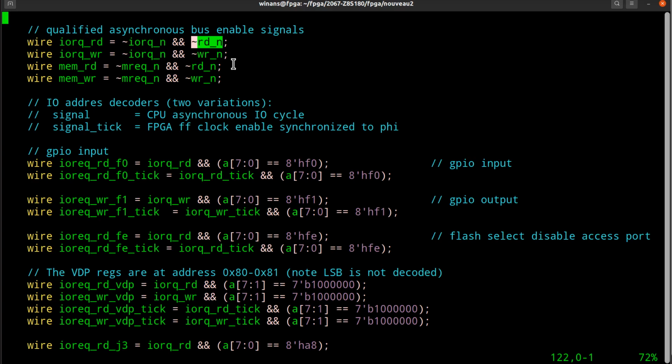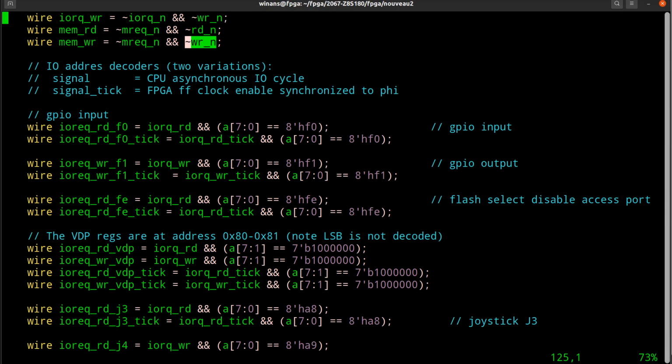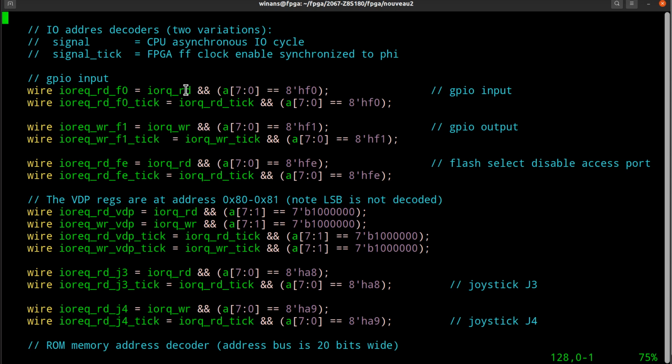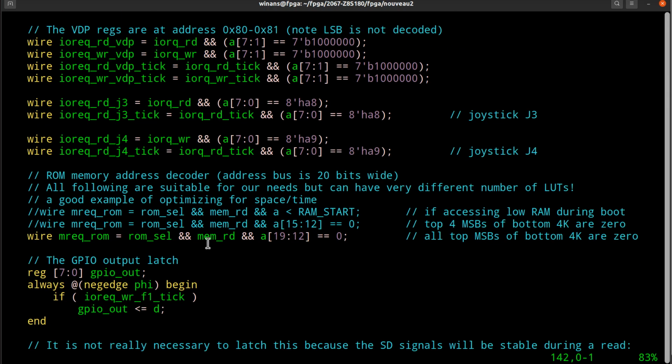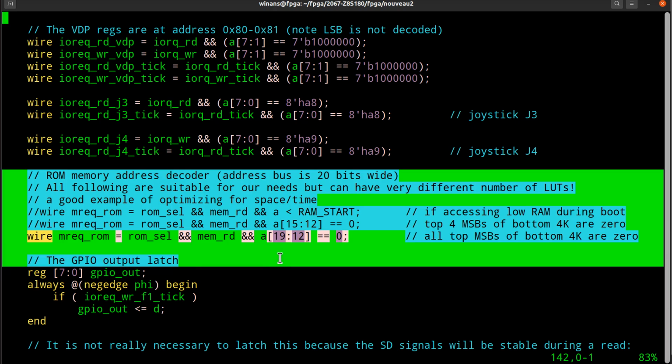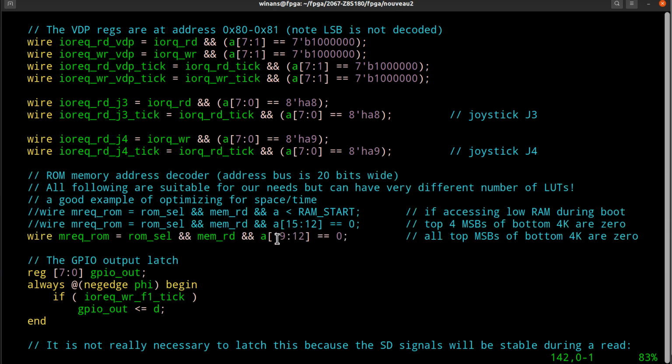And we just look at all the waveform diagrams, and you can see these are the situations you care about. Memory request is true when I'm reading. Memory request is true when I'm writing, and so on. So I end up with these four signals to control these logic functions down here. And you can see IO-rec read, IO-rec write, read, and so on. Mem-rec or mem-read gets used somewhere right down here. This is when I'm talking to the ROM, the boot ROM.